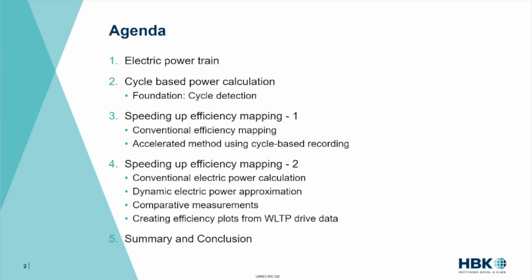The first real-world example I'm going to explain and explore is how to speed up efficiency mapping with a method which is called cycle-based recording. And then further on, I will elaborate on a second method to speed up efficiency mapping by using dynamic electric power measurement. Both together will allow you to significantly shorten the test time you spend when you test a drive, when you characterize a drive, when you do mappings.